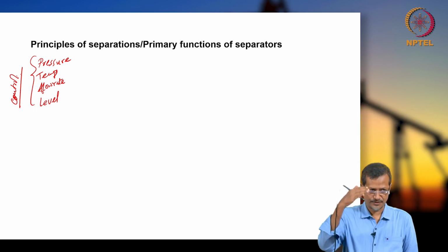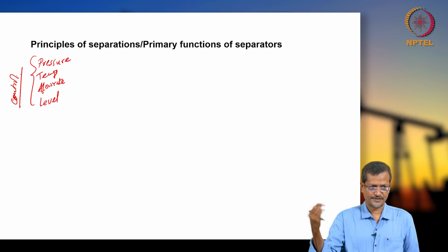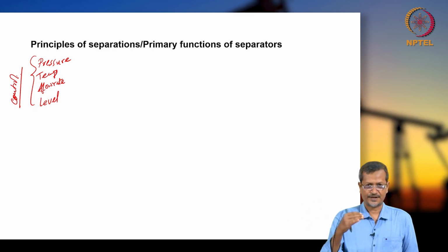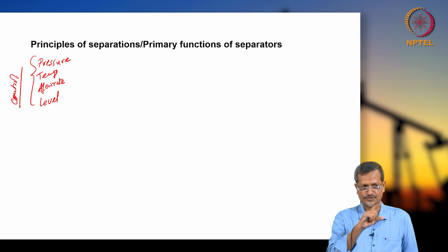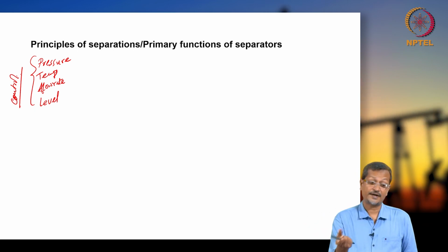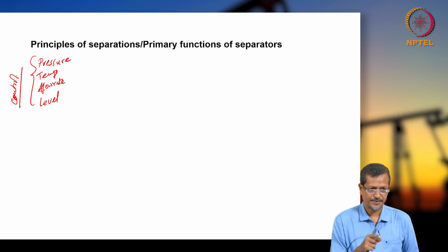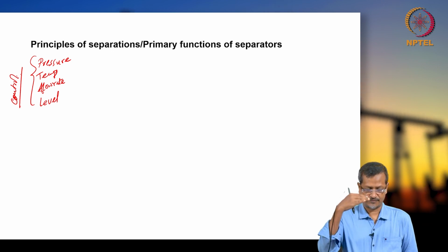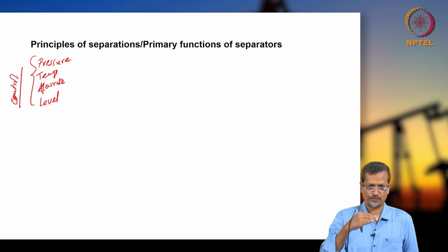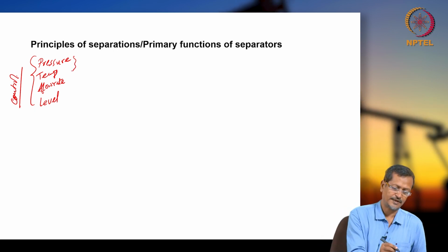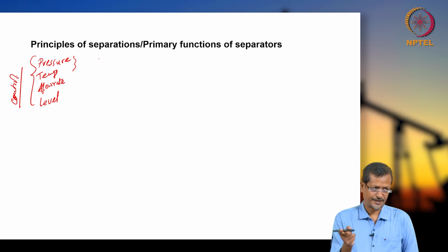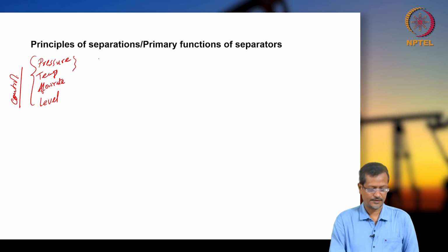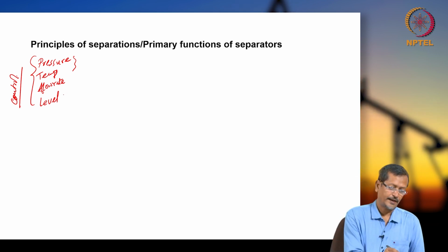If there is any leakage, then pressure can drop quickly, or if there is some blockage somewhere, things are not working because of sand deposition, or maybe some failure somewhere in some valve, like an automatic safety valve. In that case pressure can rise in a certain separator. So, if pressure is changing, then your separator system may not work, or the whole piping system may not work, or it can be dangerous also. Okay. At the same time, temperature also you have to look at, because pressure and temperature are linked actually. If pressure is down by, let us say, 100 psi, maybe temperature will be down also, because pressure and temperature are linked by the gas law, you can remember, PV equals nRT, right. And flow rate normally you do not control. If you control pressure, then normally flow rate also will be controlled relatively. And another thing is the level controller.